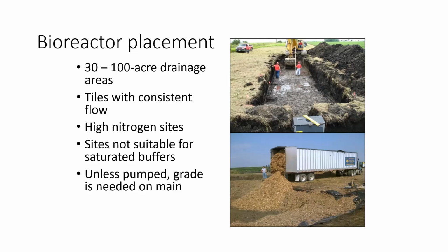When we're looking at bioreactors, we want to know that that tile has consistent flow. Even though it's an extremely cost-effective practice, it isn't an expensive practice to consider. And there is a 10-year maintenance interval where we do need to replace the wood chips. And so you want to know you're putting it on a tile that's going to have consistent and good flows coming through it.